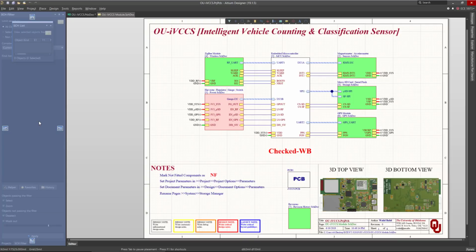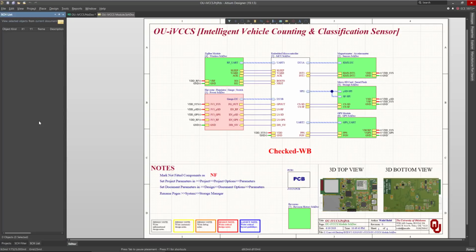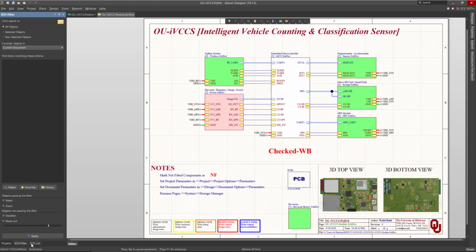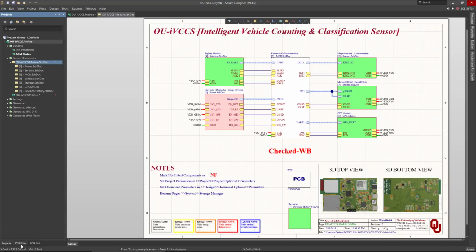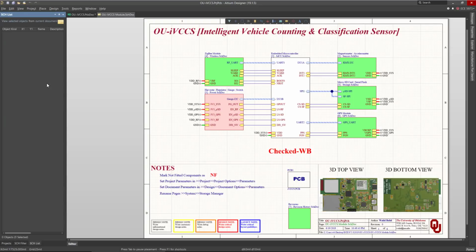Now, the entire area of the target panel will become shaded blue to indicate that the panel will become a single tabbed group. Releasing the left mouse button will group the panels together, and you can cycle between the panels from the tabs in here. So this is called tabbed panel grouping.